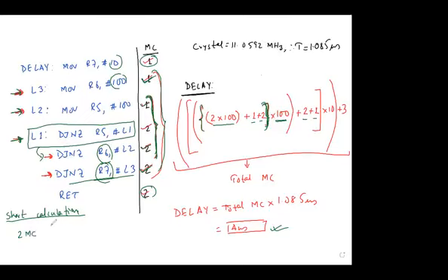So just write 2 machine cycles. How many times can you execute this? Let me show this for this example, then you will automatically understand. So 2 machine cycles, how many times will it run? We have got 3 levels. That means it will run for 100 into 100 into 10. Now you multiply with 1.085 microsecond. Whatever you get is the answer.